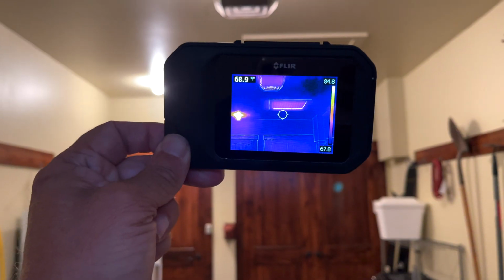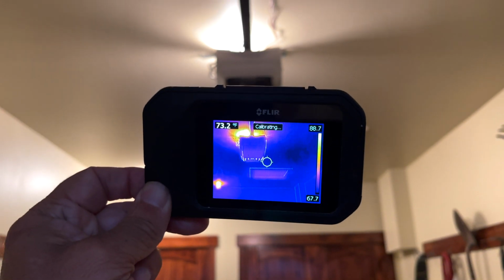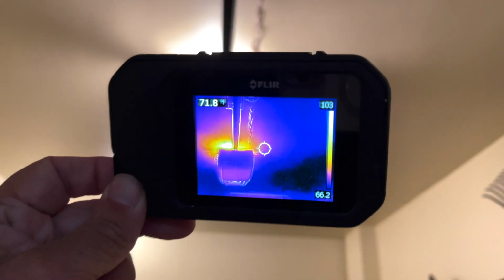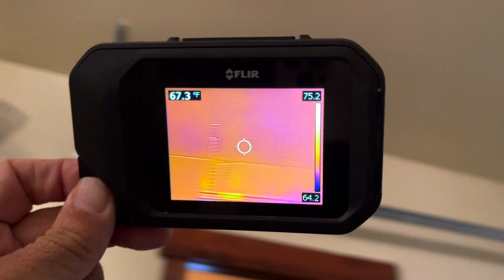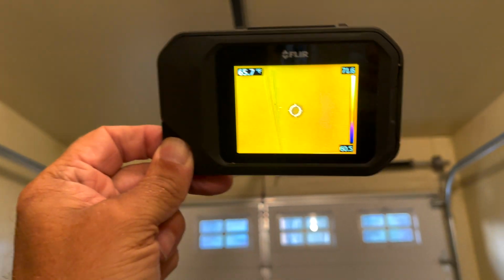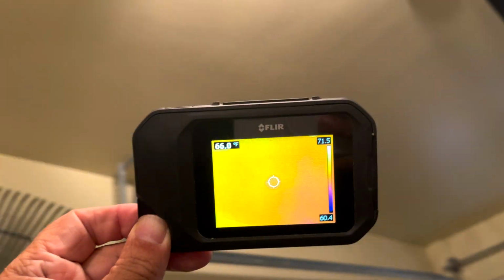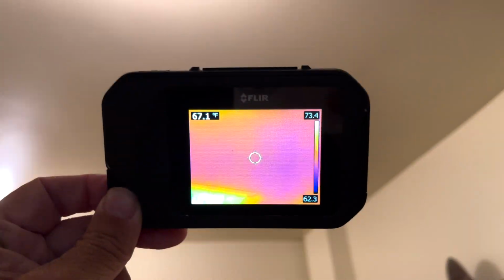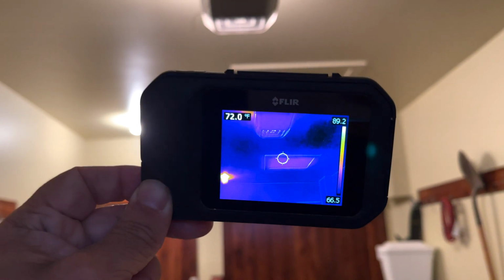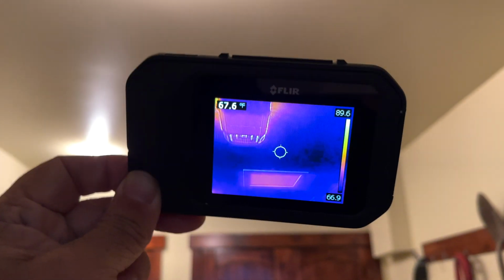Just looking around. Sometimes I'll give my client the infrared camera to look around. Garage door opener is warm. It's hot outside. Nothing going on with the garage door itself, but the attic access is on fire. There's no insulation there, and it's a fire hazard anyways.